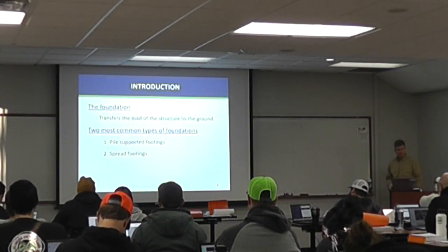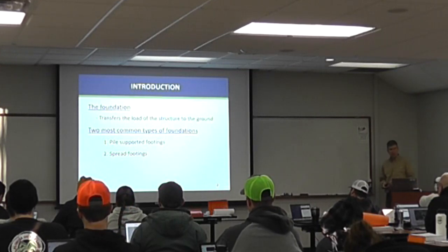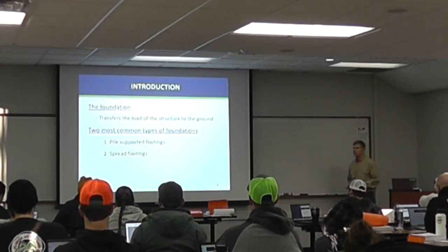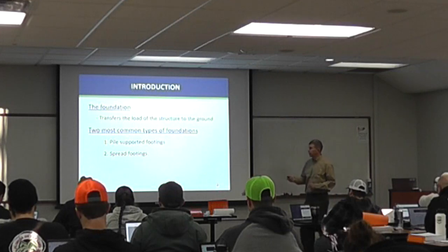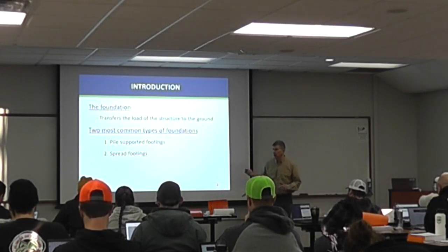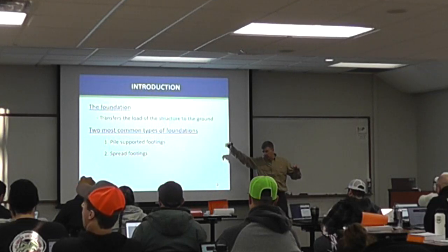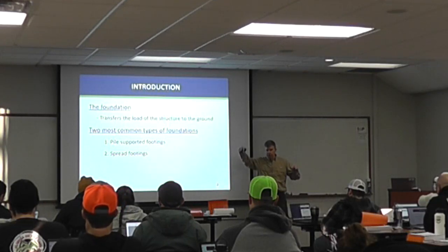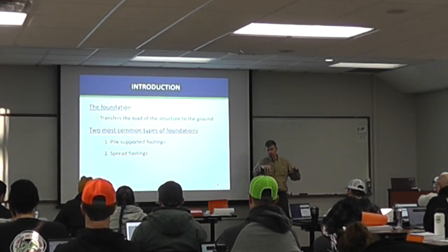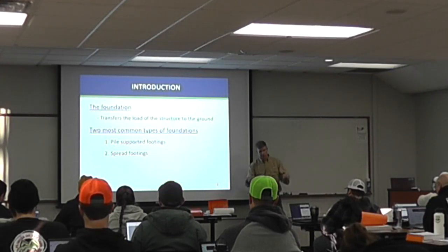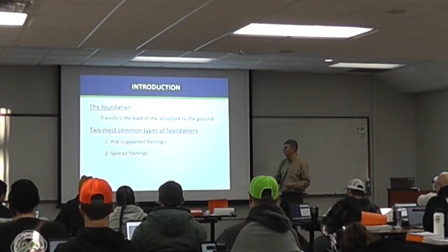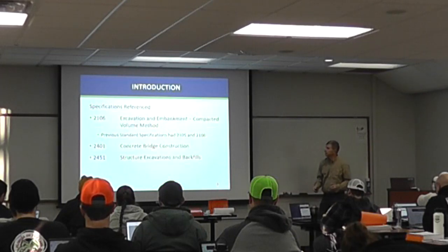So the purpose of the foundation is to transfer the load of the structure to the ground. We can do that through piles, as we talked about yesterday, or spread footings. Two different methods, but in each way, the load that's out on the bridge, coming through the deck, through the beams, down to the pier or the abutment, down through that to the footings, and then from the footings either to the pile or to the spread footings.